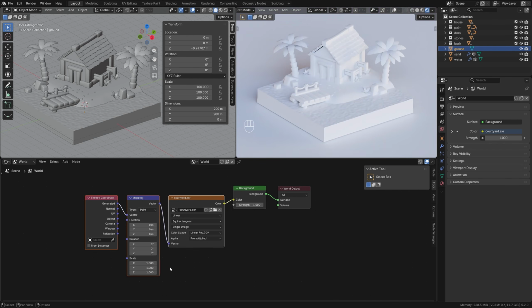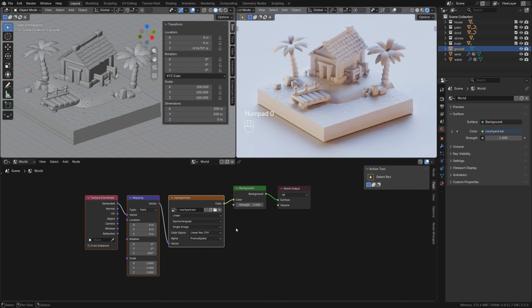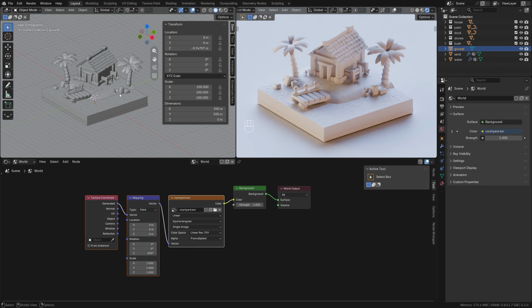We open it, and here rotation along Z. We set 200 degrees, and in this way, the HDRI map will shine in the following way. Right now, when light appeared in the scene, immediately all flaws are visible. Well, firstly, the floor needs to be raised a little along the Z-axis. We raise it a tiny bit so that our scene is located on the floor.